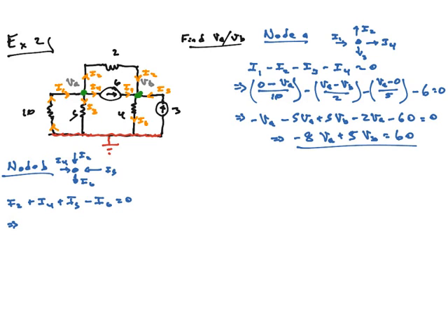All right, I2 from the top. Do we know it? No. So what did we do? We went from A, so it's VA, got to B, minus VB, divided by the resistor it hit, the 2 ohm resistor. All right, I4. We know I4. That's good. I4 is the 6 amp source, so he's 6.